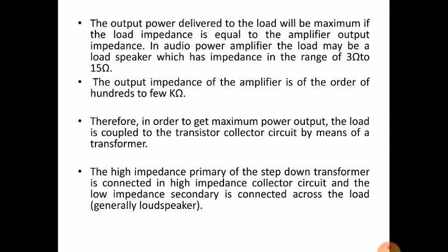Now the output power delivered to the load will be maximum if the load impedance is equal to the amplifier output impedance. This is impedance matching, the concept of impedance matching, and this is a theorem. If you can remember from the subject Basic Electrical Engineering, there is a theorem, the maximum power transfer theorem, in which there should be an impedance matching.